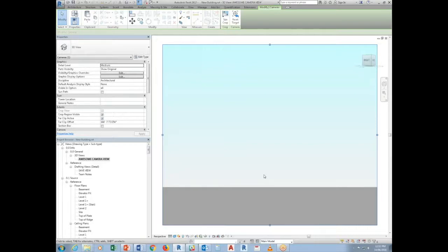This is basically before 2016, when we have a building that has different elevations. You cannot rely on elevation 1, because when you paste them into that elevation 1, it changes the height in relation to level 1. So what I did is create level 0, select that and say copy from level 0, then go back in there and paste it into the same level 0.